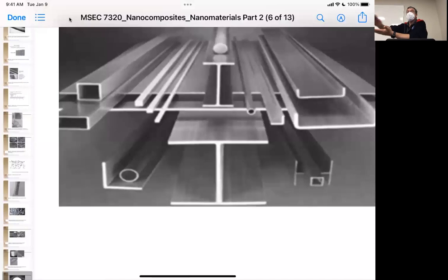It's easy to smear it. And so by having this slightly harder layer of oxide on the surface, anodizing is one way to do it, but you can do it in a nanostructured coating with this, and it'll still give you some better, less galling effects and less corrosion effects from motion. All right, questions on that?